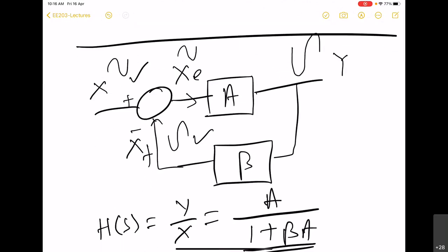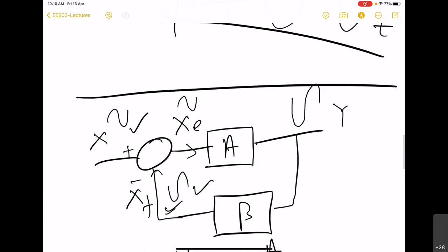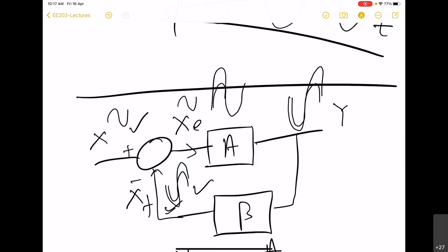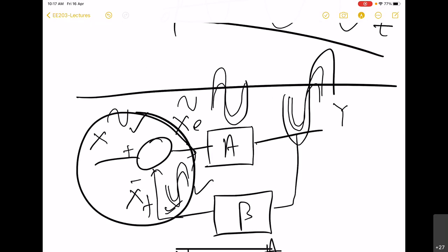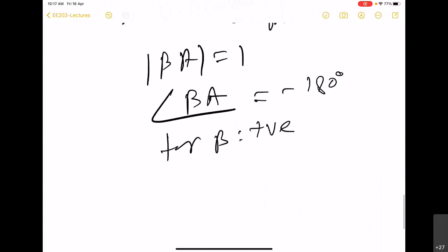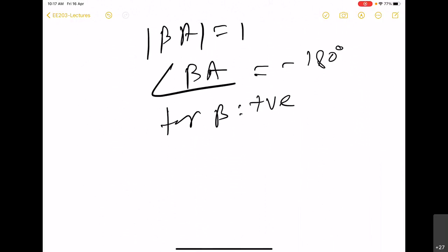That means basically this will get added, and what we will get here is a larger signal. So if the larger signal is fed to the amplifier, you will get a still larger output like this. So this will lead to even larger feedback, then even larger input, and so this phenomenon will grow on. So what is happening here is on the input side, addition of the feedback signal is taking place with the external, and that is causing the instability.